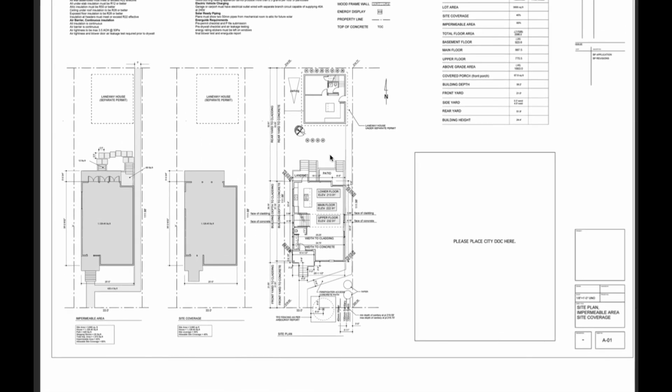I just got a huge lumber delivery, and I'm going to stack everything down here. But if you're still in the forming phase, you're going to need to form this concrete walkway at some point. So maybe that's not the best place to be stacking all of your wood. Maybe you should stack it back here at the back of the house, just so it's out of the way, so you don't have to move it twice. Those sort of things, thinking ahead, keeping the project rolling, is going to be really important, especially if you can get a set of the plans from the builder or your boss and really look through those things and start to get a better picture of what you're dealing with.